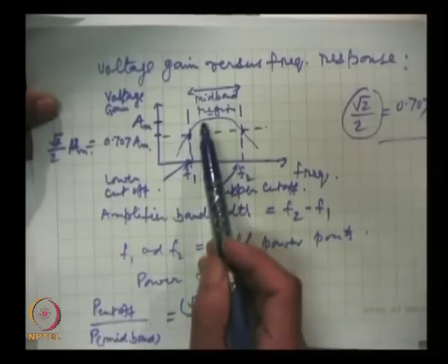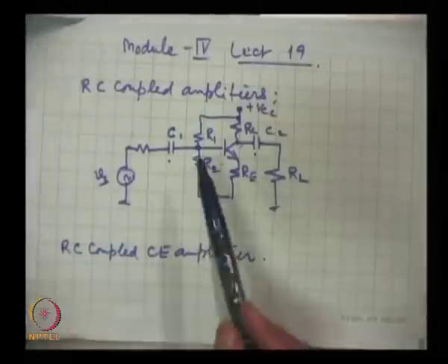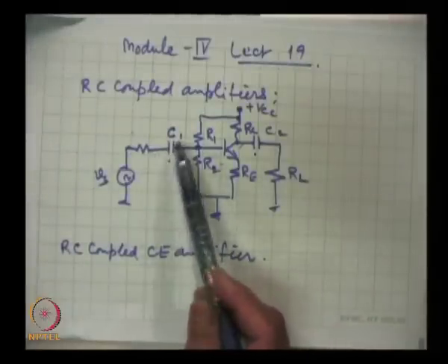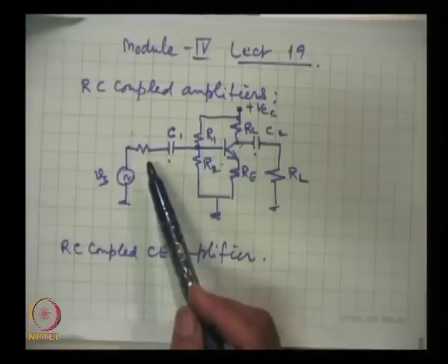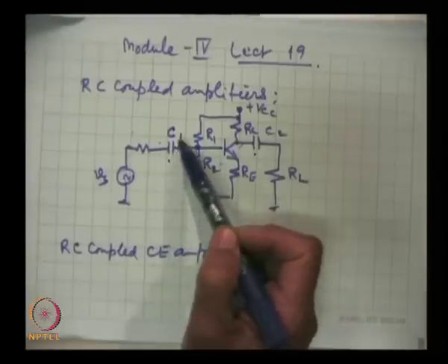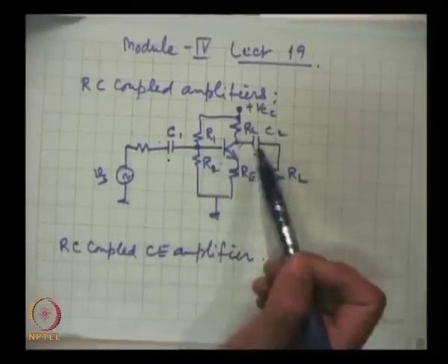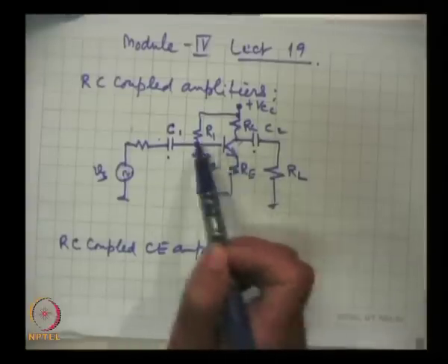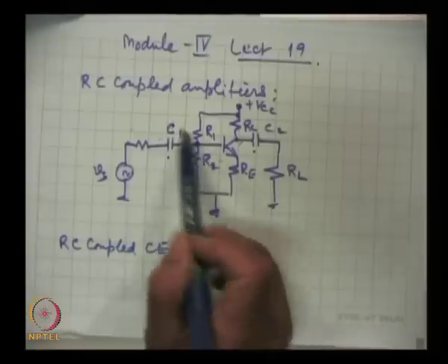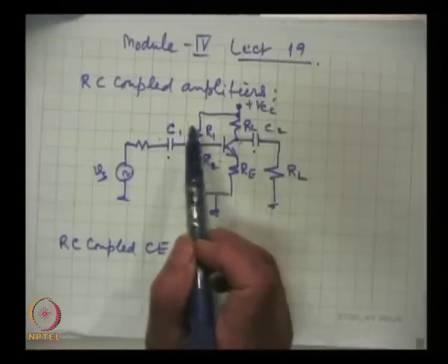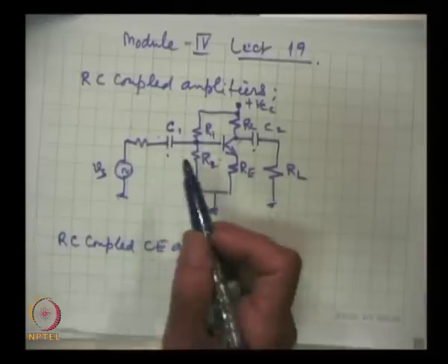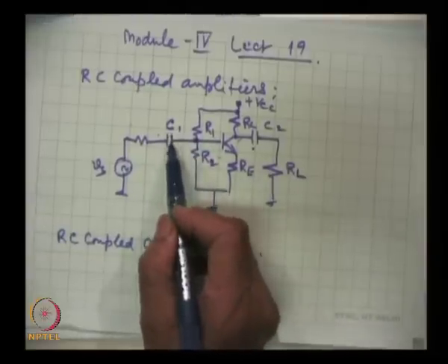But as we decrease the frequency, the reactance will gradually become more and more important. There will be larger and larger signal voltage drops, and whatever signal drops here is not available at the input of the amplifier. That is waste, not recoverable. This is not desired, but anyway this is the evil necessity where we want to couple.